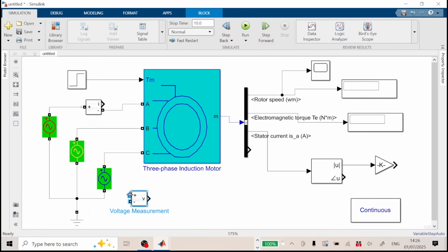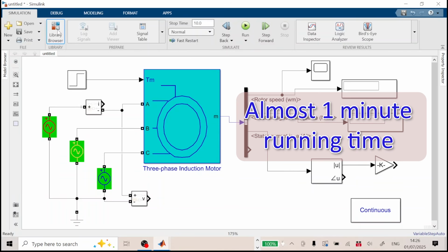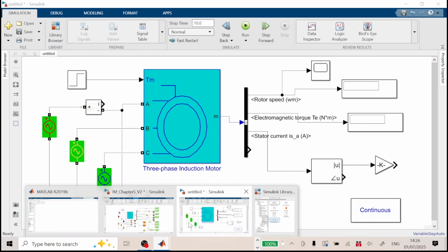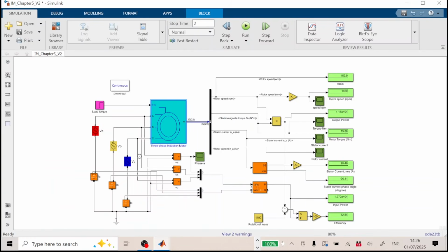So if I measure between this point and this point, that one is going to measure the phase voltage. So if we put a scope here, we're going to measure phase A voltage. So now we can drag from measurements a block like this one. Return back to our block here. We have the ammeters, we have the voltmeters, we have 3 voltages, we have 3 currents. We can apply that one to a block like VABC, IABC to measure the power.